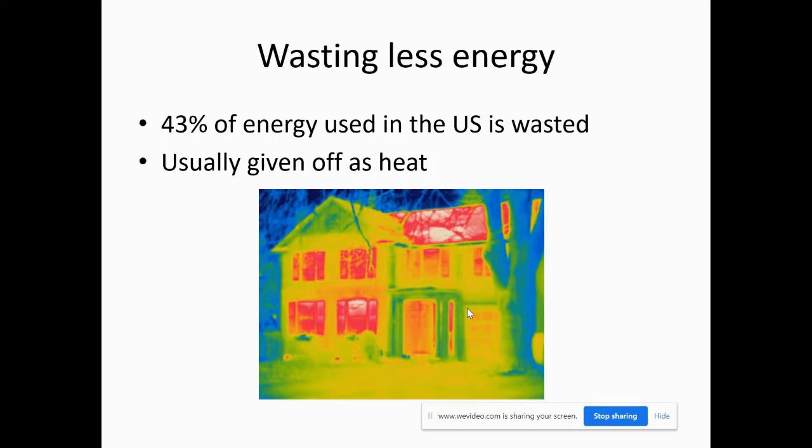But in the case of the US, here's the thermal picture of a house. Wherever you see red, they're wasting heat. That means the heat's leaking through. Those are single pane windows, and some yahoos decided to vault the ceiling in their master bedroom, forgetting that they needed to insulate afterwards.